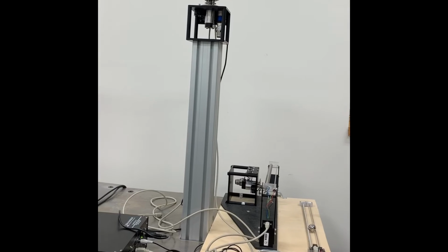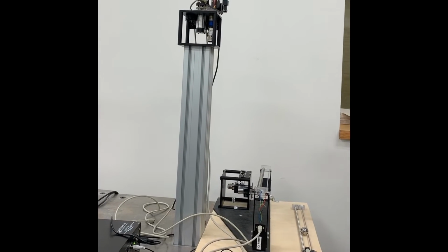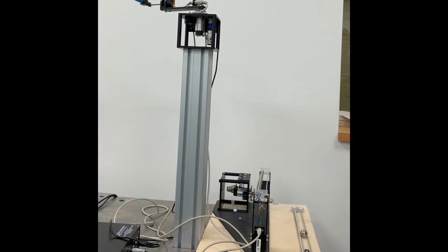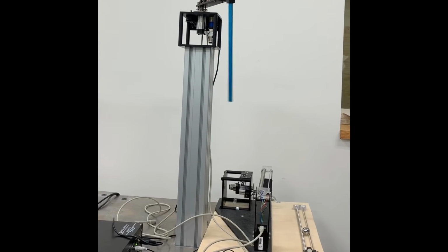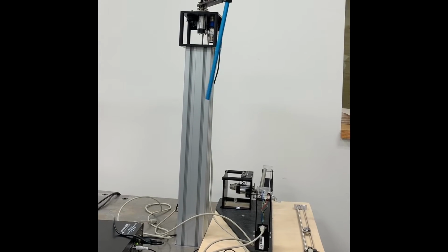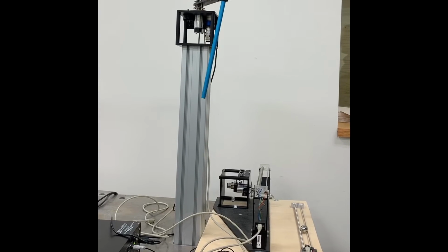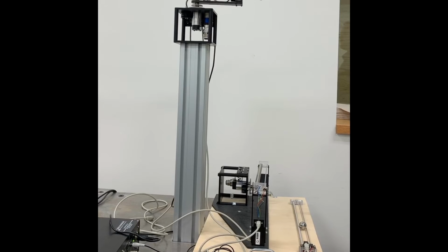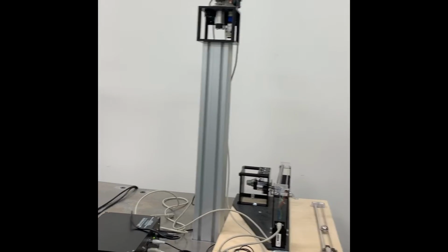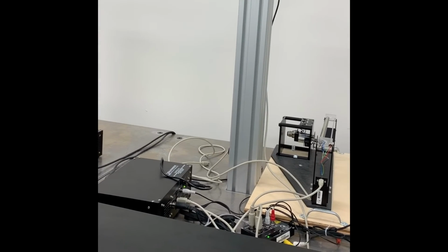For the swing up stage, position logic was used to make sure that link 2 was at or near the bottom of the swing within a threshold which we set at plus or minus 10 degrees. Velocity logic checked that the velocity of the rod was within plus or minus 0.1 to ensure that the pendulum had proper time to settle and reduce variable error before swinging up. Additionally, there was a stage check to make sure that the previous stage was at stage 2.